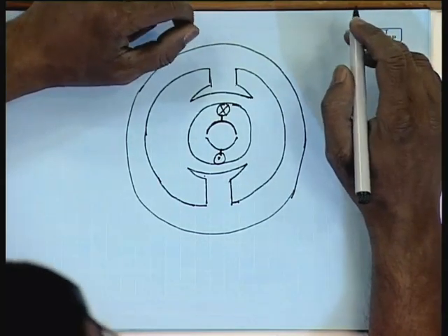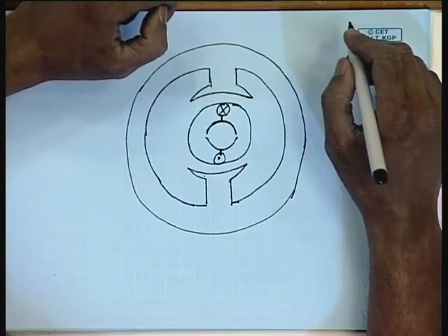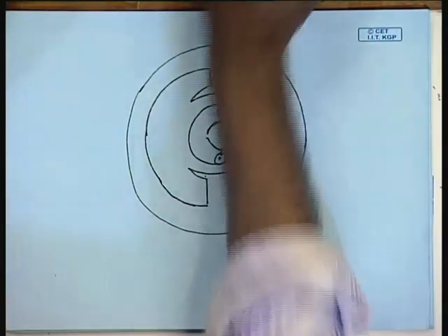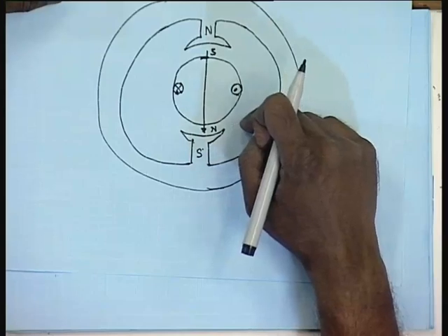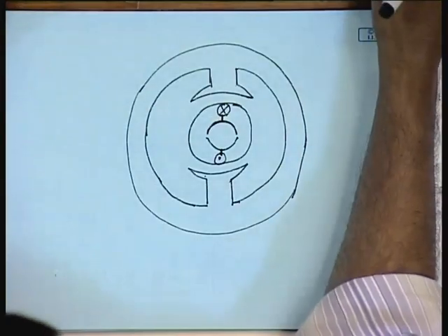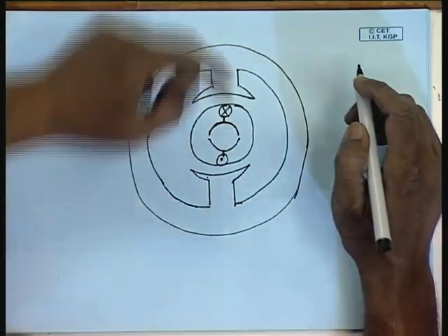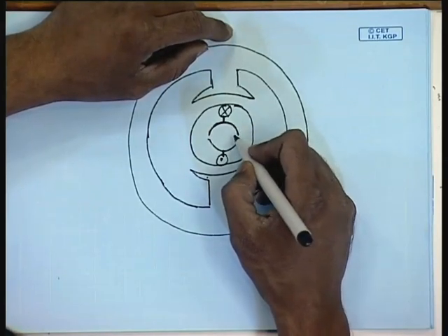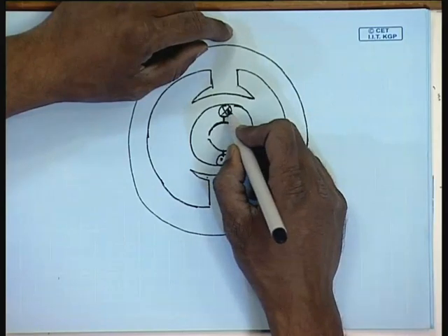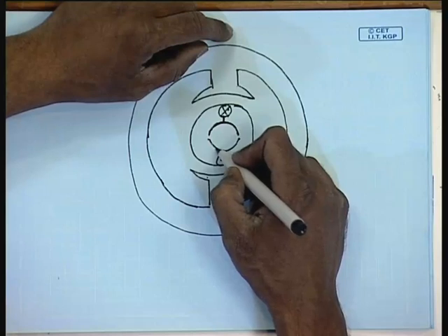Where should be the position of the brush? The position of the brush should be such that in the aligned position it changes the polarity of the current flowing through the coil. Therefore, for half the cycle they should connect to one commutator, and the same brush should connect to the next commutator for the other half.